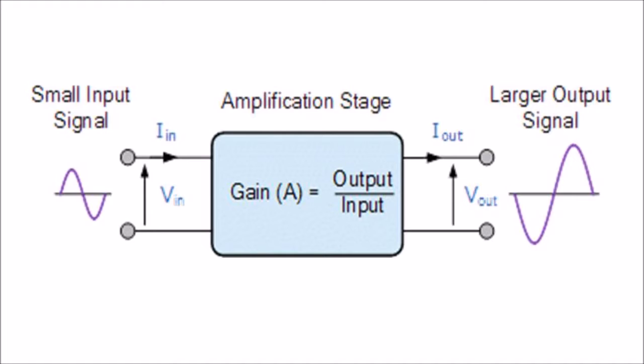All types of transistor amplifier operate using an AC signal input which alternates between a positive value and a negative value. So, some way of presetting the amplifier circuit to operate between these two maximum or peak values is required. This is achieved using a process known as biasing. Biasing is very important in amplifier design as it establishes the correct operating point of the transistor amplifier, ready to receive the signal, thereby reducing any distortion to the output signal.